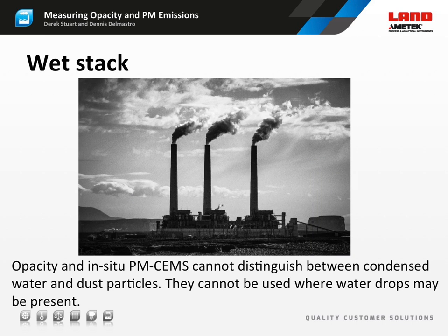A problem common to all opacity and in situ PM-CEMS is that they cannot distinguish dust particles from water drops. That means they cannot be used anywhere there could be condensed water present in the sample. That's not a problem in most traditional applications, but the increasing use of wet flue gas desulfurization, or wet FGD, means there are a lot more wet stacks than there used to be.